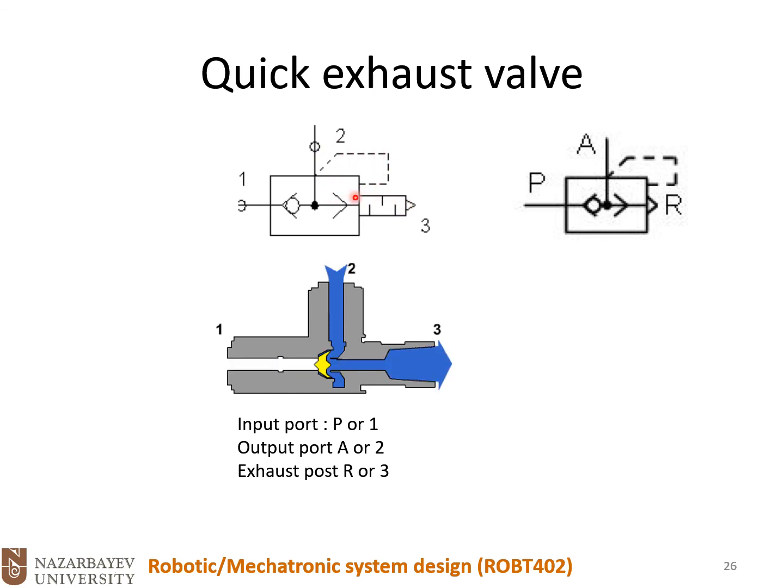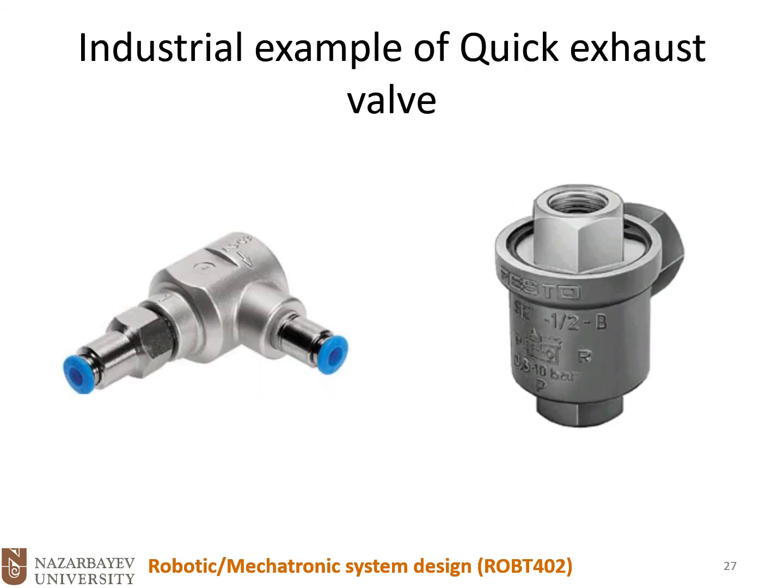If this, let's say, signal or dotted line is an open one, it means that this is a pilot valve, and this is one separate signal valve that should be pressurized by a separate line. However, when we have the closed line, it means that we don't have a separate pilot port, but the airflow passing inside the valve will change the status of the valve. Okay, so let's see what is the application of these types of valves.